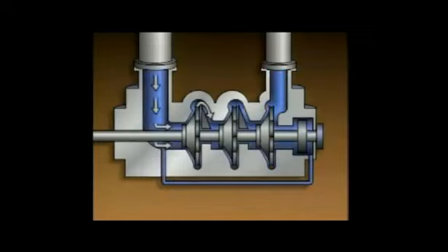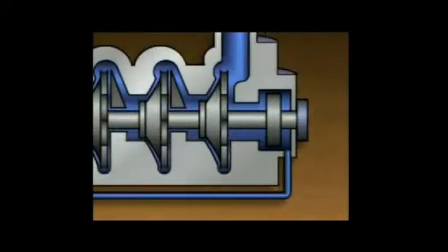As the liquid passes through the pump, its pressure increases, and it exerts a push on the impellers in each stage. This push, or thrust, is caused by the difference in pressure between the suction eye and the volute. The thrust is directed toward the suction eye. In order for the pump to operate properly, the thrust must be offset.